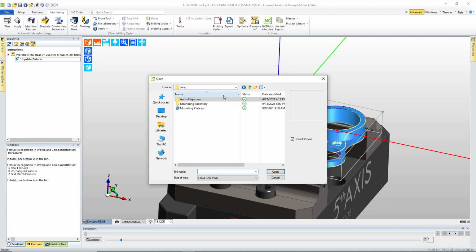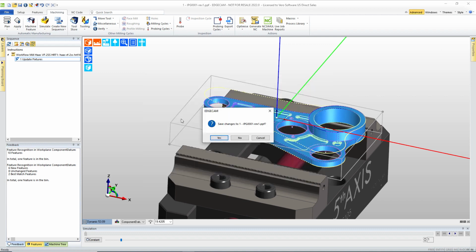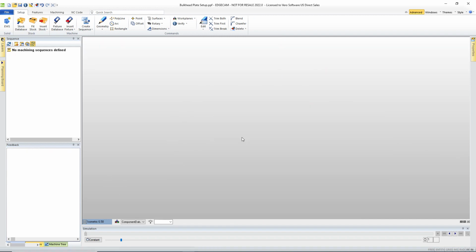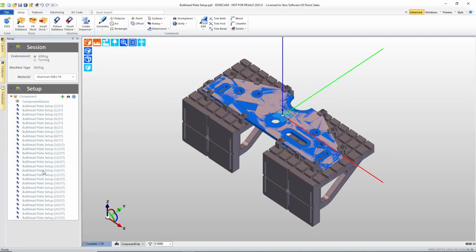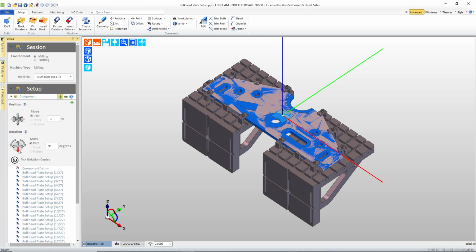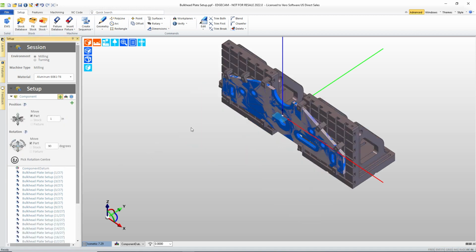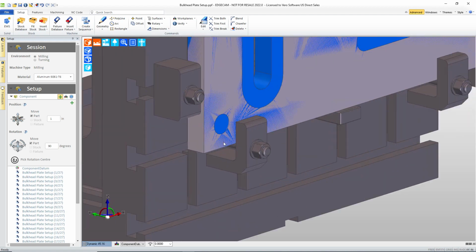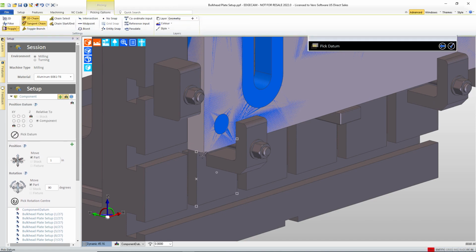Let's open another file that will look at what would happen if we had a CAD assembly of the entire machining setup, and how would we work with that. Up to now, we've looked at individual solids where we add the stock, add the work holding in Edgecam. So in this case, the CAD work's already been done. We've got a part that's been cut in a flame cut or water jet. So we have a piece of material that's going to be specifically located on a couple of angle plates. There's some stops here, and we're going to set a 0 point based on that.